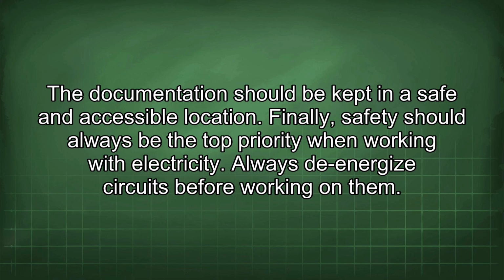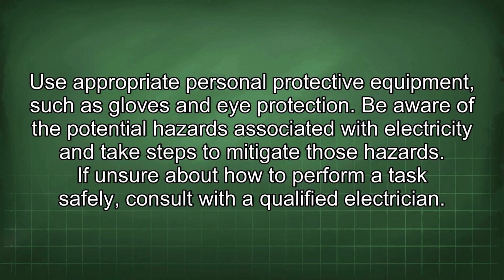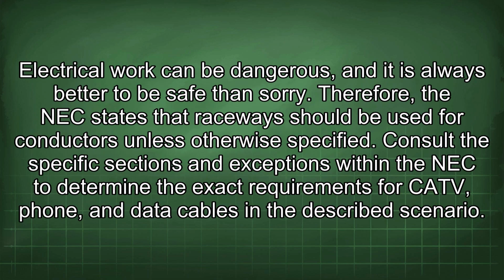Finally, safety should always be the top priority when working with electricity. Always de-energize circuits before working on them. Use appropriate personal protective equipment such as gloves and eye protection. Be aware of the potential hazards associated with electricity and take steps to mitigate those hazards. If unsure about how to perform a task safely, consult with a qualified electrician. Electrical work can be dangerous, and it is always better to be safe than sorry.